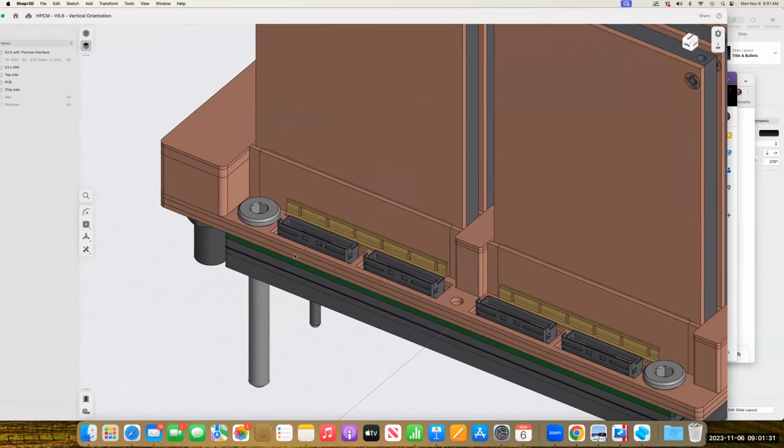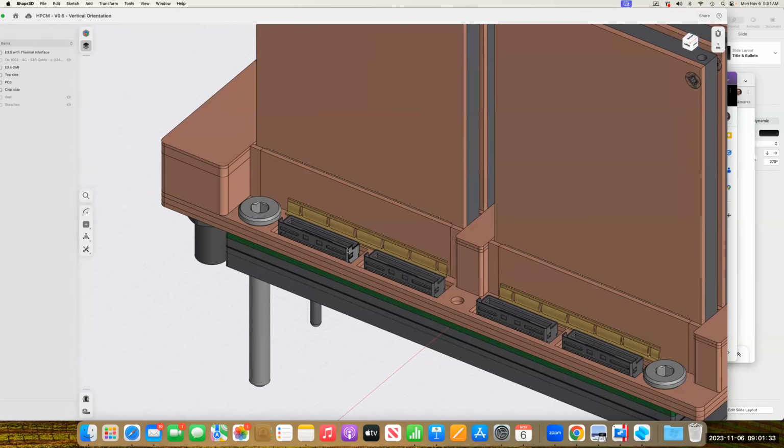I've shown this as an MCIO, but MCIO can't get us to 112 gig speed today, and you need active. Should we just switch over to somebody else's, like Samtec or Molex, that can do 112 gig, and put the PCIe over there? And how do we deal with the impedances? We've got lesser pin count, and clearly we want these connectors to be as small as possible.